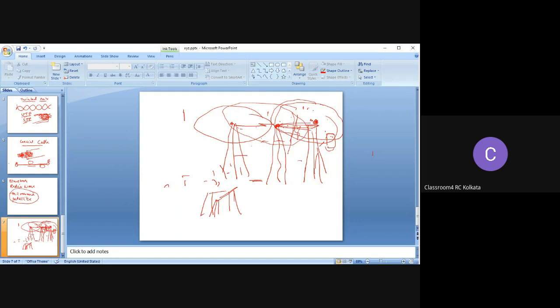So microwave travels in straight lines, and so the transmitter and receiver stations should be aligned with each other. We know that the earth is curved, round in nature. So if you install two towers at the same distance, it is not an easy task. You need to raise and lower the tower and align these two points properly for line of sight, a straight line.